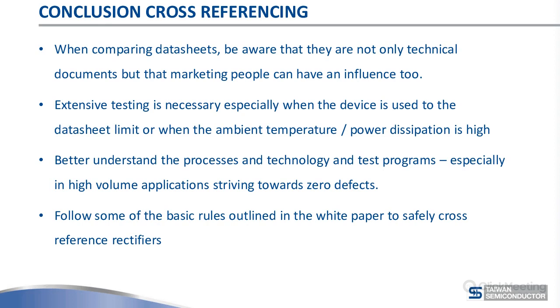It isn't. Testing is necessary when the device is used to the datasheet limit, or when the ambient temperature or power dissipation is high. If you have conservative designs, your testing should be limited or can be quite modest. If you're actually using it at high temperature and to the limit, you may want to test extensively, not just one or two parts.